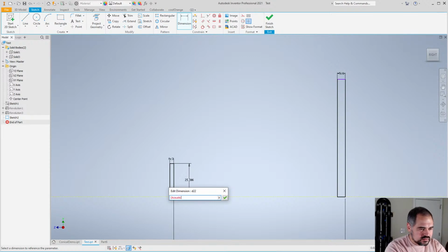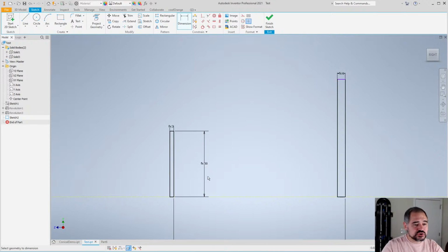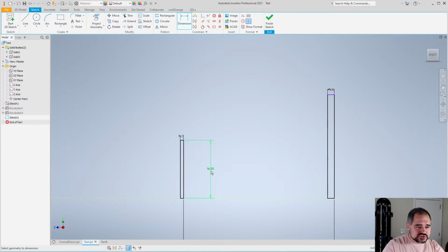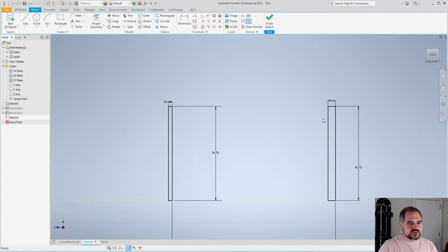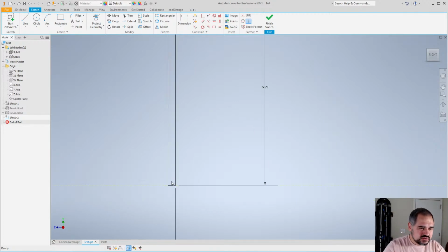So what I'm going to do is I'm just going to say, let's say, acoustic length times taper times 2. So that's 2 times the bell radius, safely larger than we could need it. And actually, I'm going to bump that up to 3. And then here, I'm just going to set that to the same thing. So it just needs to be larger than it could ever need to be.